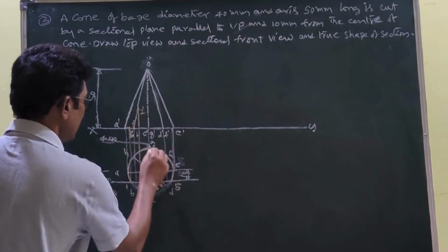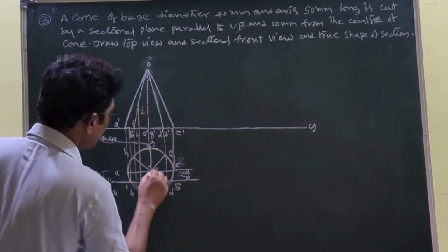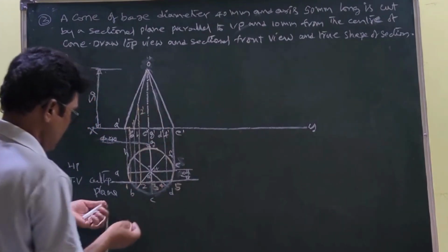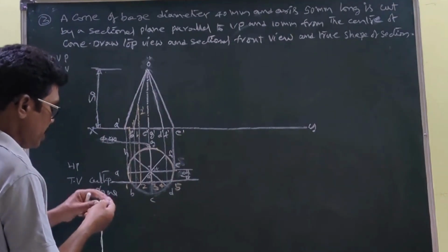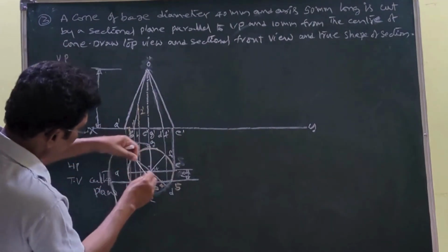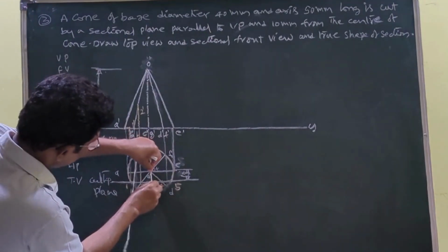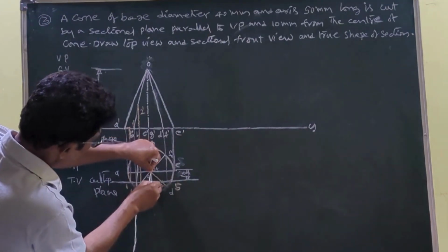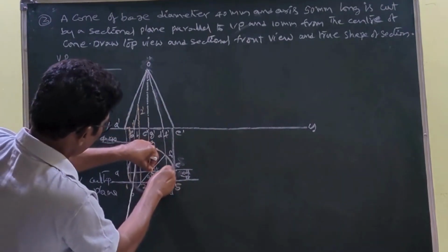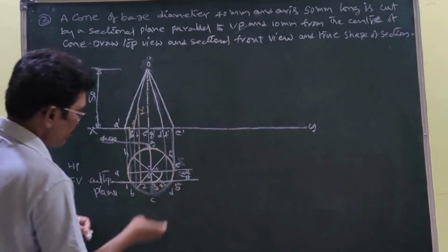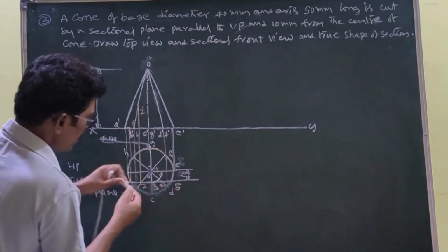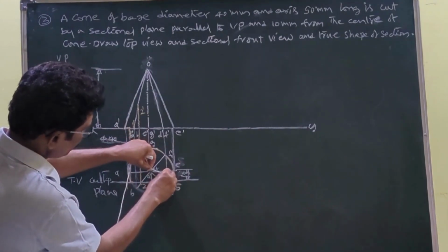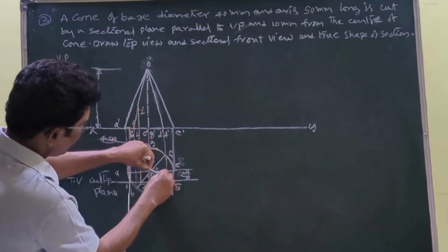Next this is the cutting here. This is the axis line. So from this it is perpendicular, we cannot locate this point on this line. So therefore what you have to do here, you carefully listen. You draw an arc like this horizontally. This is the center, this is the radius. You draw the arc on this horizontal diameter.